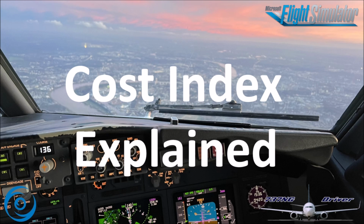Do note that when we say that for the cost index 0, minimum fuel in the climb, it does not mean that it is going to be actually the least fuel consumption. However, it is going to be the minimum contribution of the fuel used up in the climb to the total trip fuel, which is different from the minimum amount of fuel that you could use to reach your cruising altitude.